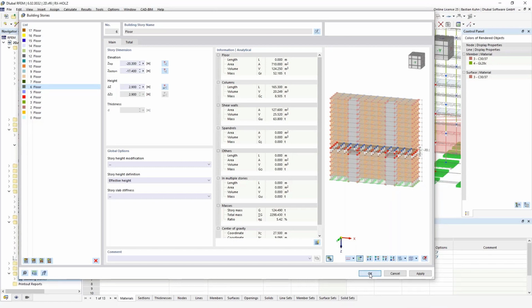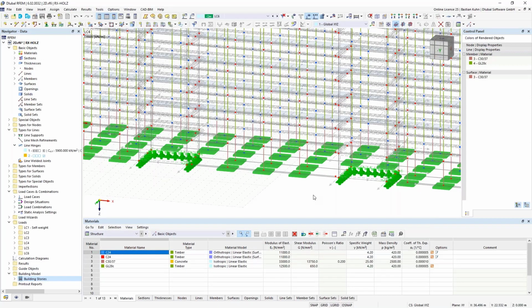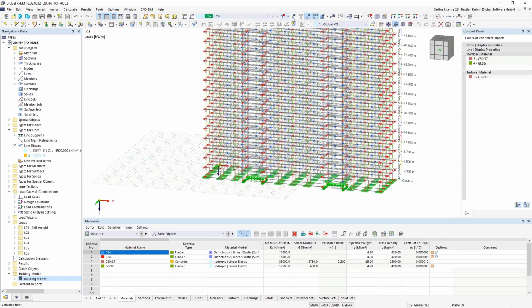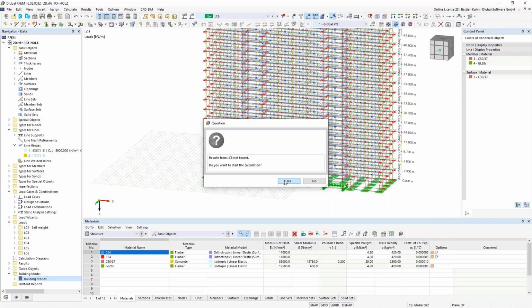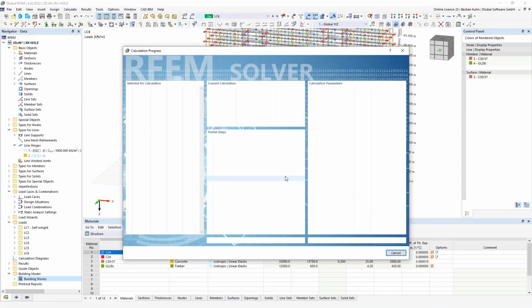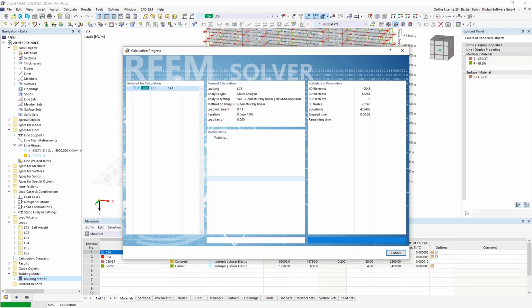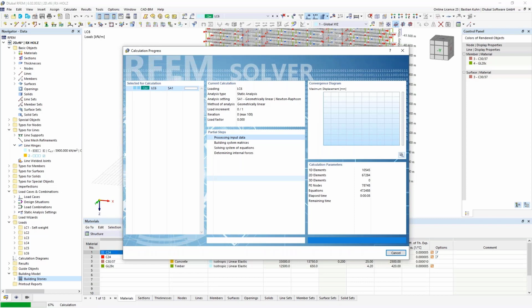Then we say okay. And now what I said already, what the advantage is for the analysis and for the results, is that you get additional masses and columns where you can get the force in every story, in every wall. You get a force that's transferred into the wall that you can read out. That's actually the theory behind this add-on building model.